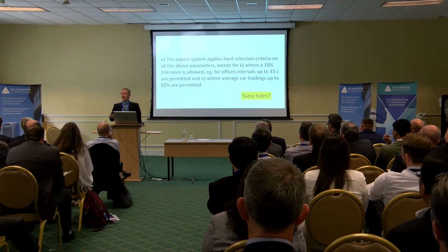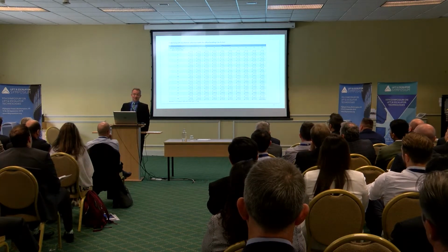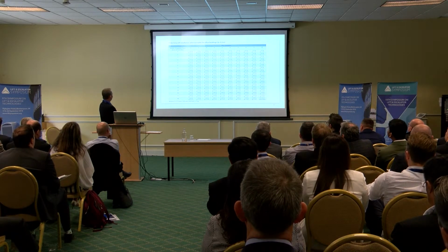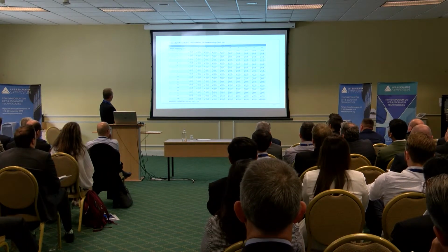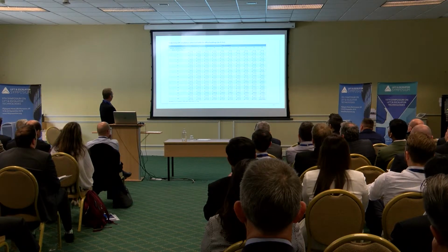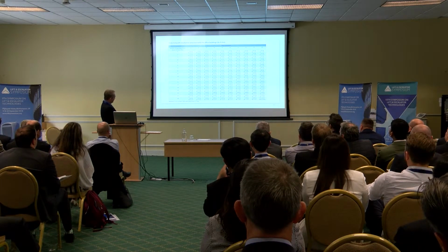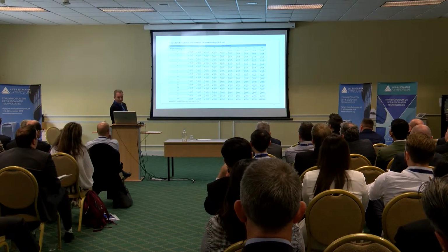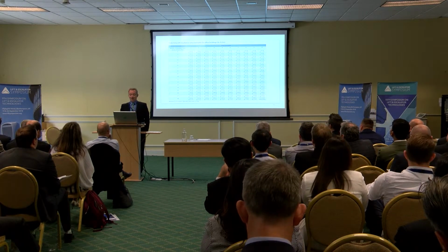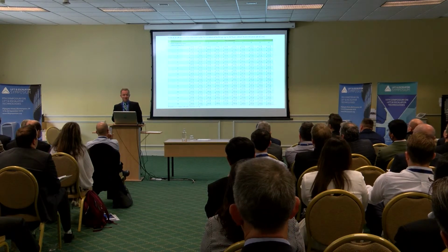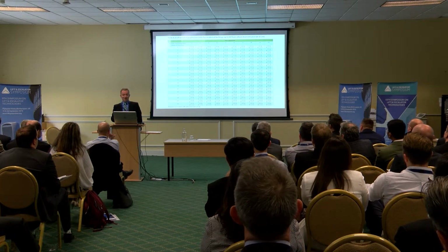Having done that, software will generate all these tables. So you can literally say, this is for an office building, 3.3 meters, and then 12 floors, 30 people per floor, then 450. Notice that's the smallest car size. We'll come back to that later. That's a hotel building and a residential building.